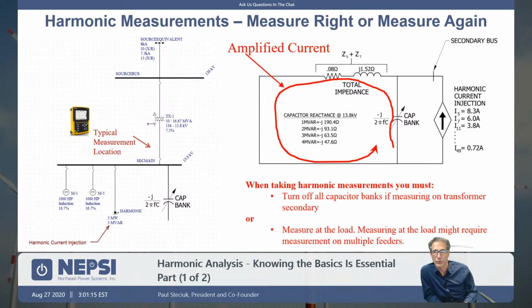And then with voltage harmonics, it is very difficult, and I think what you're getting at here is how to take care of ambient voltage distortion. Generally speaking, I do the analysis assuming 0 voltage distortion on the transmission grid, and my primary concern is: what am I, as the industrial customer, or if I'm doing a study for the industrial customer, what am I producing for voltage distortion in my plant, and is that result going to be an issue or not?